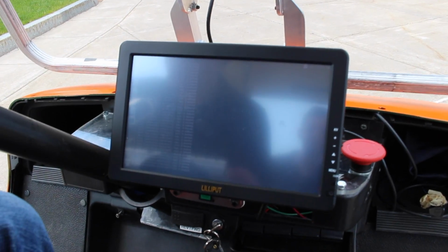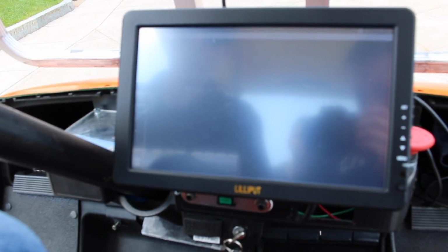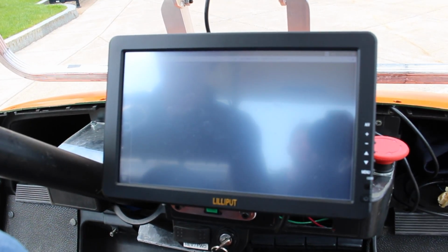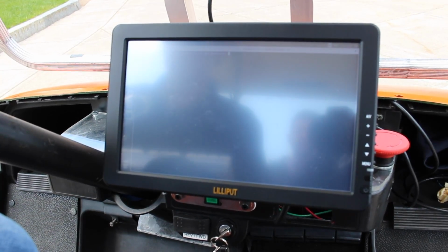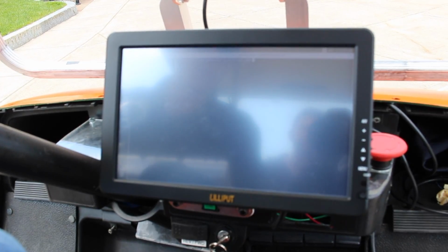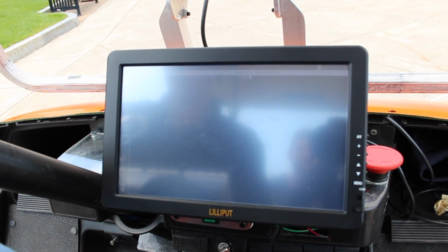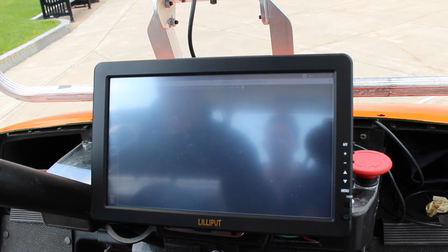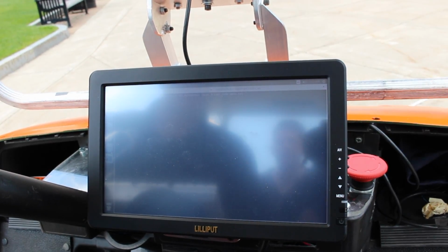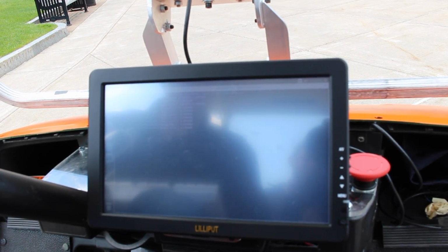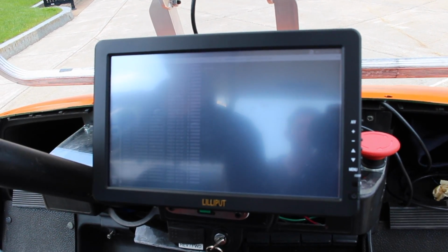You can see we're at 0, 0, and now I'm going to press Control-Shift-T and open up a new tab. Now I'm going to do rosrun APM_autonomous and then the local driver node, and this is where you give it the text file. We just called it test demo.txt. So at this point we have the local driver, which is going to try and follow the points file that we generated before. You can see that it's showing no angle error right now because we haven't started. And that's our odometry data, also showing at 0, 0.